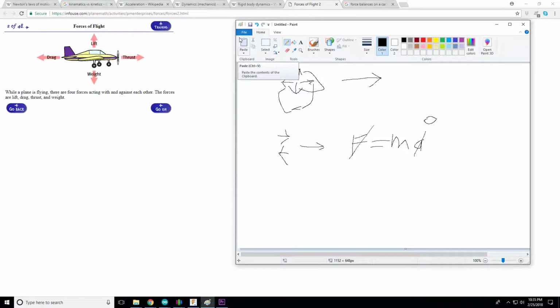Another one is lift versus weight. So again, using computational fluid dynamics, you're able to measure the lift of your wing / airfoil, your horizontal stabilizer, and the body of your airplane. So with that, you will be able to know what is your maximum all-up weight of your model or your plane, which means fuel, pilot, electronics, cargo, everything. Basically, what are you taking off with?